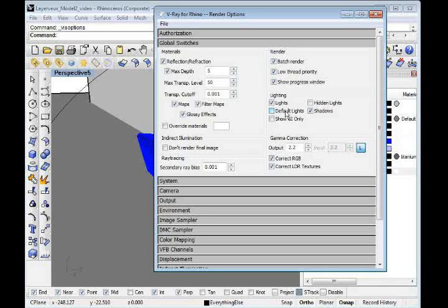Default lights are either lights that are default by Rhino or by Vray. You want to have that unchecked because you may want to change your own environment within the building, an object, or details in any particular way that you've had set up. So you may not want the default lights that are already set by Vray. Or you may, so it's up to you whether you check it or not. And then check the show GI only, and we're about to hit this part next. So just go ahead and have that box checked.